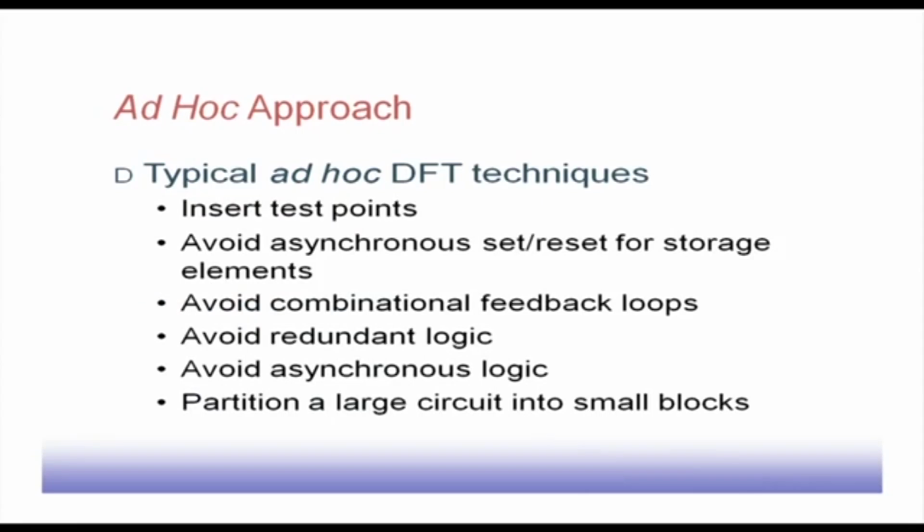So, we will start looking at the ad hoc approaches. Typical ad hoc techniques are like this: insert some test points, and avoid asynchronous set/reset for storage elements. If there is asynchronous set/reset, then when we are trying to design a test pattern, all of a sudden a reset pulse may come to the flip flop and the flip flop gets reset. Naturally, that cannot be accounted for in the testing process. So if my design can be constrained so that I do not have this asynchronous set/reset, then it is better.